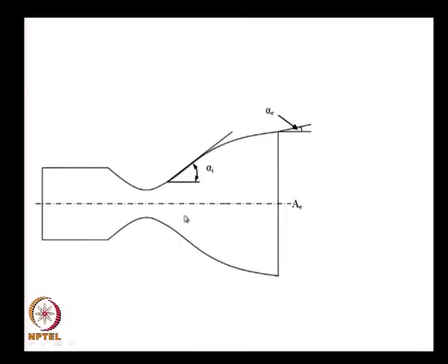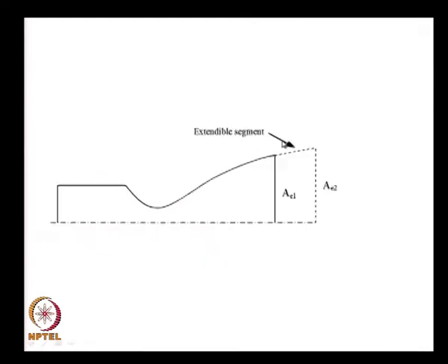We talked in terms of a contour nozzle. We told ourselves instead of having a cone, I initially expand the flow to alpha I, between 20 to 15 degrees, and then bring it back. I have a low angle over here at the exit of something like 2 to 5 degrees or so. Smaller the angle at the exit, smaller is my loss.